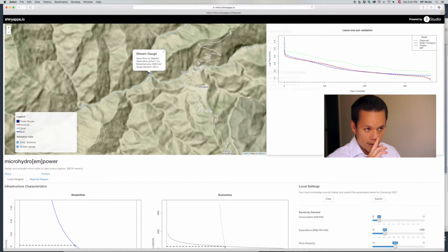And the way this method works is that you go there on a day in spring, in April, when it's supposed to be low flow. You measure the flow, then you assume it's low flow, and you multiply it by a regional factor. And the problem with this method is that you have to assume that the flow you are measuring on the specific day is the lowest flow you could get. And of course, it's very rarely the case. So that's why it's often overestimated.